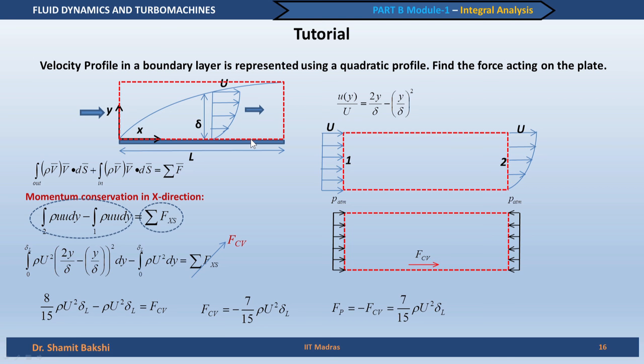Actually, you can think about it. This is about getting to a quantitative value for the force, but physically if you look at it, what happens here? Let us understand the situation. So, we see that this is the control volume. In this control volume there is a momentum of the fluid which is coming into the control volume. So, this transmits a force in this direction, and there is the momentum of the fluid which is exiting the control volume.